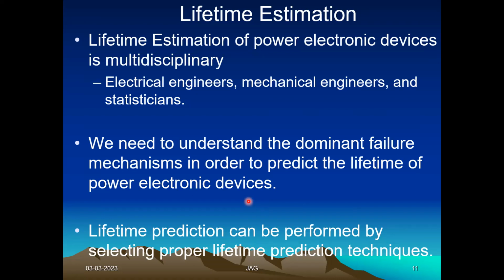What I would like to tell you is such abuses will definitely degrade the components. Instead of 10 ampere, I pass 11 ampere for 7 microsecond. The device will not fail, but it will be degraded. Its life will be decreased. Its performance will be inferior.